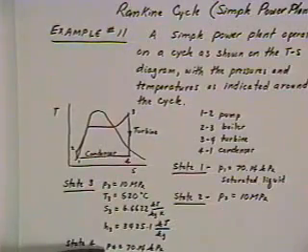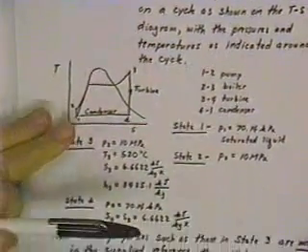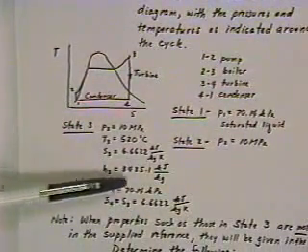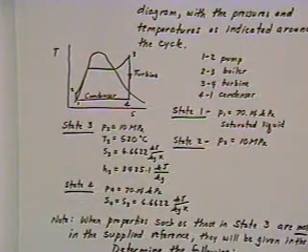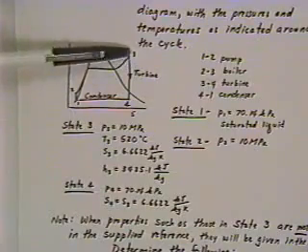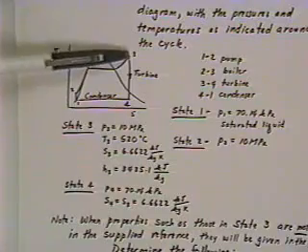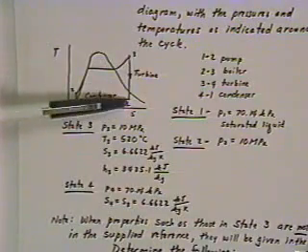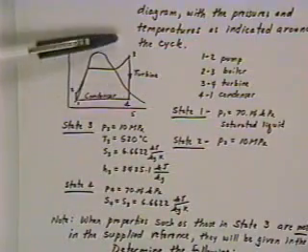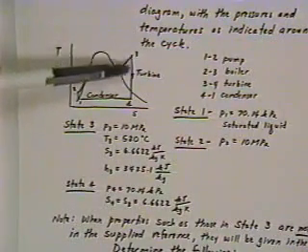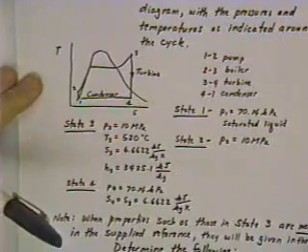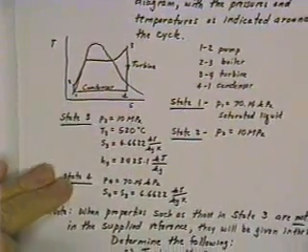And State 4, we're given the pressure conditions here and entropy conditions. And we're given that in our very simple cycle, highly idealized, the turbine work from 3 down to 4 is reversible, so that the entropy is constant from State 3 to State 4. So this is an isentropic expansion through the turbine.